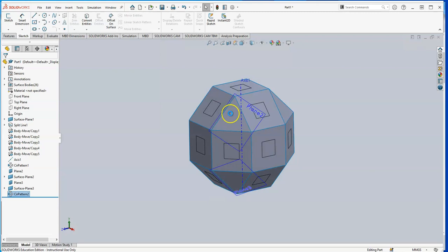So while we're going to be creating a hollow object, for the CFD analysis of this, it's only the air inside that we're going to be modeling. So we need to create it as a solid, the solid representing the air inside. And we're going to look at heat transfer through the air. So we need to turn this now hollow body into a solid. Once that's finished saving, what we're going to do is take all these faces, knit them into a solid.